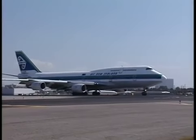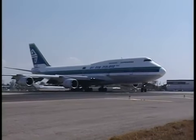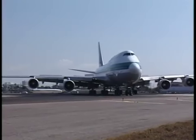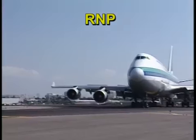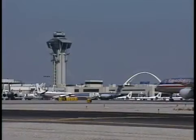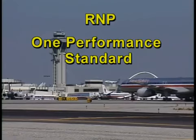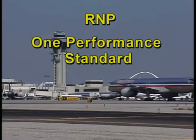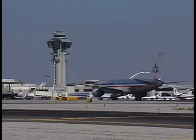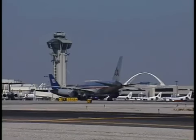To capitalize on the potential of these new technologies, the FAA, in conjunction with the International Civil Aviation Organization, ICAO, has introduced a new standard of navigation and airspace management called Required Navigation Performance, or RNP. The theory behind RNP is to establish one performance standard that applies to aircraft, airspace, pilots, air traffic controllers, and international aviation authorities. This single performance standard is enabling the widespread use of area navigation, or RNAV.